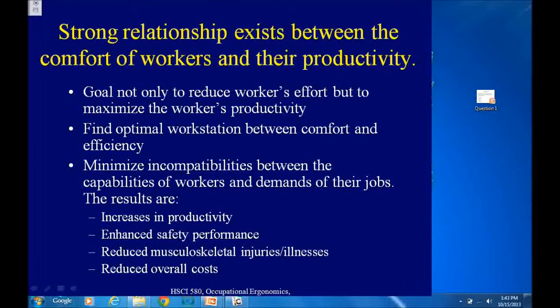That make sense? In other words, if I designed for this threshold right here, and this design was for a 5th percentile female, then the top of this threshold would be here. But because I want to design it for all people to be able to clear under, including that 95th percentile male, then we're looking at putting that threshold up higher, or to see where it is right here. Does that make sense? So you could do it here for smaller people, but no, I'm not talking about the range. It should be designed from here to here. I'm saying for all people now, it should be up here. That make sense? You'll be tested on this, so make a note of that.